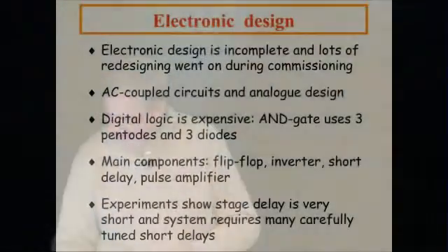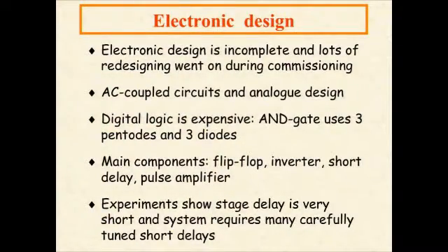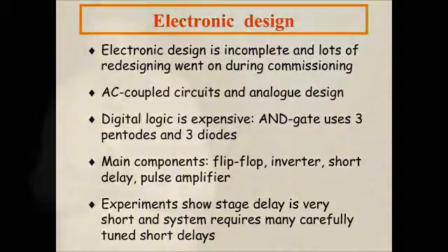I've done logic simulation. Electronics, that's where we have very little information. It's all what's known as AC coupled circuits. Any of you who work with modern electronics, you live in the world of DC coupled circuits. 0 is a reference voltage, 1 is a reference voltage. Everything is smoothed out with capacitors. All your pulses are nice and square. If you're working in EDSAC, you're always thinking about waveforms and adding and subtracting waveforms. You have to think more like a radar engineer or a radio TV engineer and how the waveforms behave.